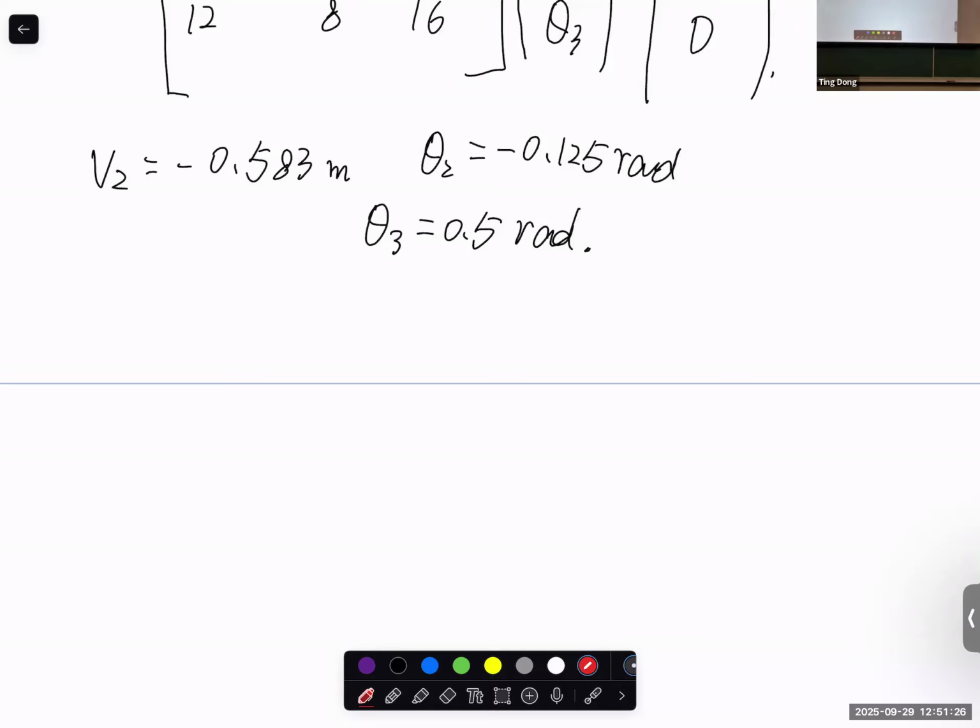So if you know your structure material, basically the Young's modulus, if you know the length of the beam, if you know the cross-section dimension, which can give you the moment of inertia, so E, I, L, you know the K stiffness matrix. And if you know the force applied on the beam or a couple applied on the beam, so in the F vector for one beam element, you know the F1, C1, F2, C2, right?